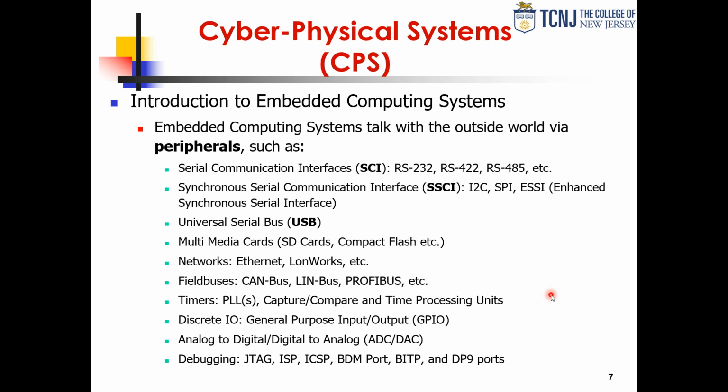So you can see that inside a cabinet, if you have a system with multiple boards, USB is a nice bus. And it's high speed as well. It had different speeds when it was conceived, from 1 megabit per second all the way to 12. But today you can stream video via USB. It's much higher than the original spec. So that one is a very important one. A lot of these embedded systems have the USB interface integrated, and all you have to do is hook up your connector, and you can develop USB applications very, very quickly.